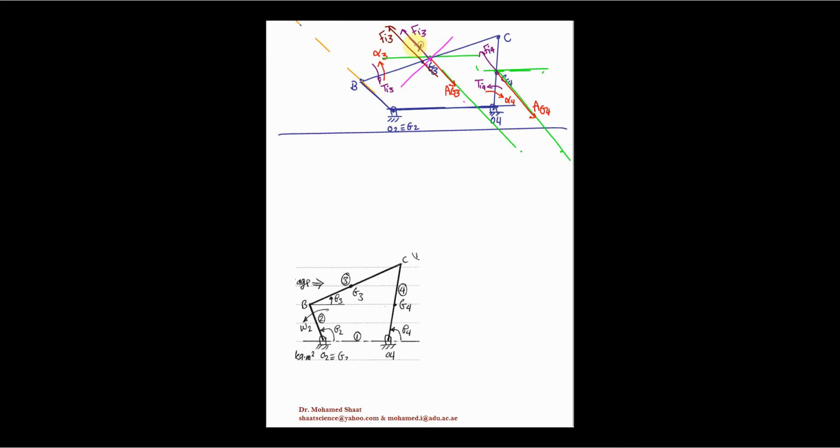And in this case, we can cancel this force and we can cancel this torque as well. So we combine both of them into this new force Fi3, which is the brown one. Make sense? And this point, as you can see, is gonna be the point of intersection of this force to link number 3. This point we're gonna need for the analysis next.